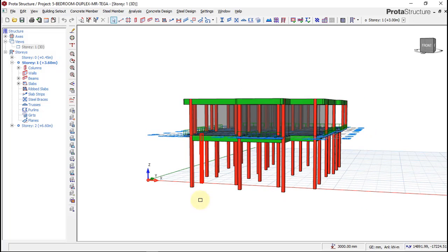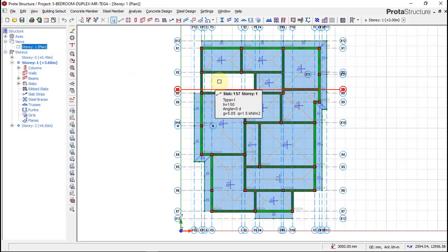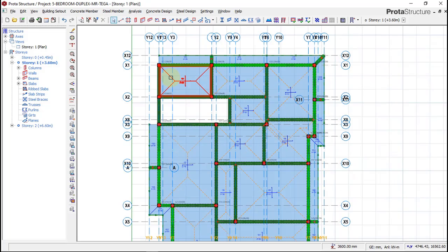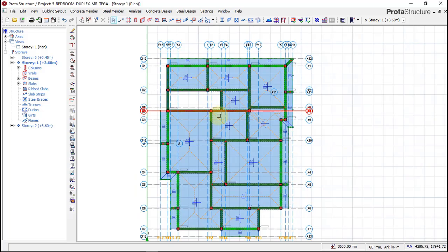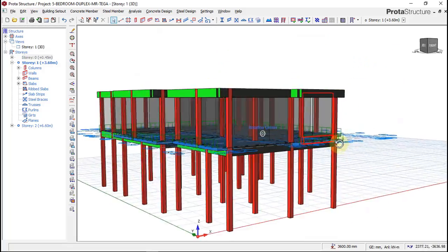This is 3.15 millimeter, and this is 3 meters. So this is how we add our story height between each floor, our story height and the difference, and editing our story. We thoroughly check the 3D and everything is in place.